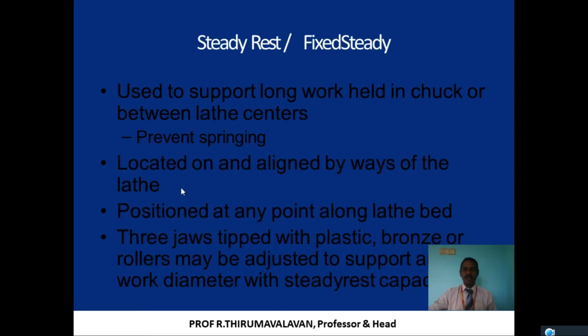The next is going to be a steady rest and follow rest. What is steady rest? What is follow rest? When you are working on longer workpieces in the lathe machine, what will happen? The longer workpieces, because of their own self-weight, will start sagging. Because of the sagging, I cannot perform the work effectively.